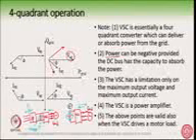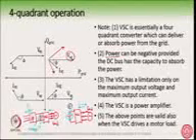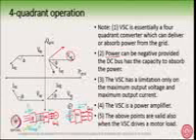In fact, to protect capacitors under certain conditions like this, we often put a bleeder resistance here, because if the voltage becomes too high, then we just dissipate that energy into a bleeder resistance.